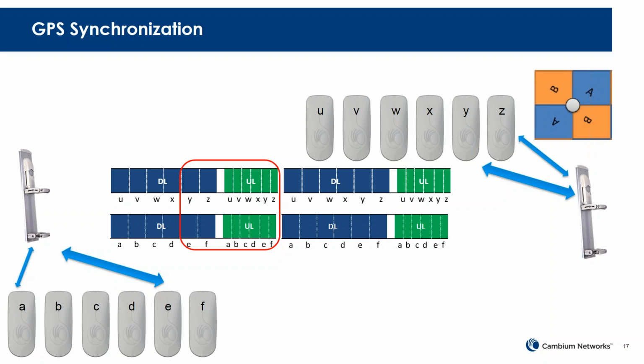And so why is this an advantage? Going back to that first technique that we talked about of actually avoiding interference and changing to a different channel, imagine how much easier it is to avoid interference when you only have to find homes for half as many channels. You're only looking for half as many channels that are clean. Imagine how much easier it is to plan around any interference you see. And so that's GPS synchronization in a nutshell.